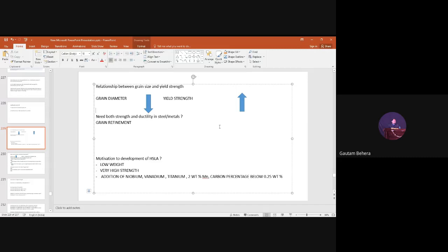This is very simple. These carbides and nitrides are still there. They are not becoming soluble. They will become soluble if you take them to a very high temperature. So that means they are still stable at 912 degrees centigrade or 1000 degrees centigrade. Stable means they are not becoming soluble. So they will be present around the grain boundaries of the austenite, right? So they prevent the coarsening of the austenite grain. They will not allow the austenite grain to become coarser. Do you people understand now? Or shall I repeat?